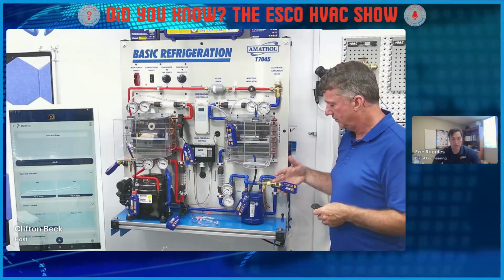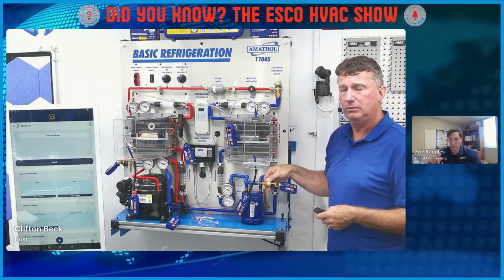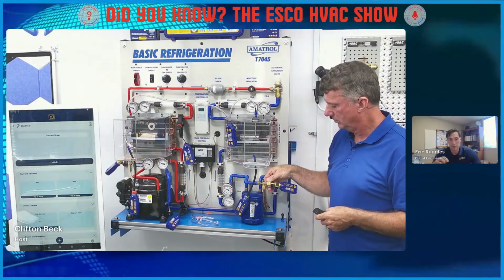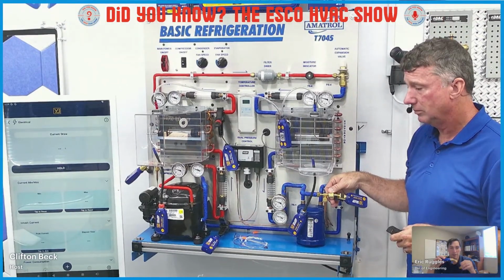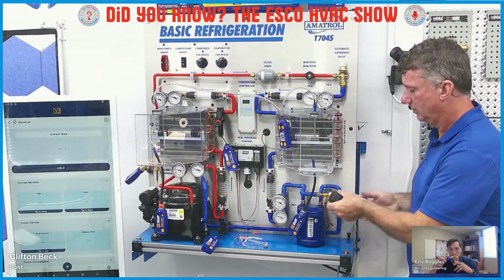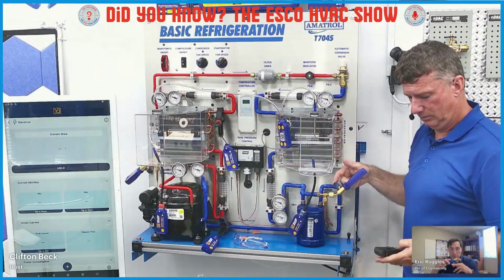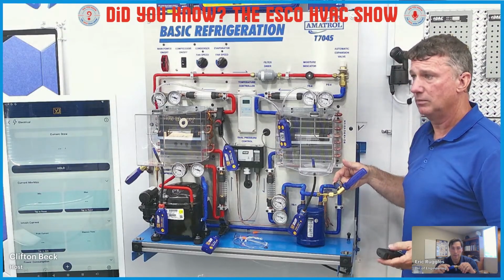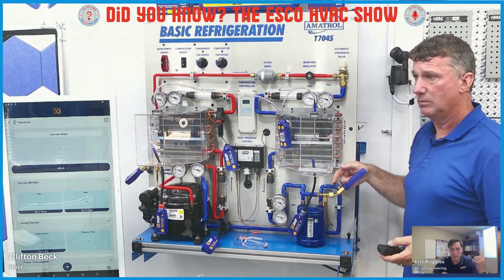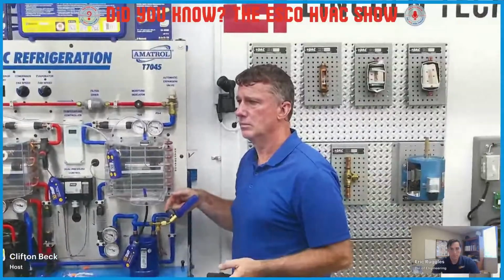So, quarter inch fittings. You can get adapters for 5/16 if you need to, but they just screw on normally with the Schrader core depressor in them. They also have an auxiliary port on the bottom, so there's a T built into it, if you need to add a hose to actually charge or anything through the system. So it's nice to have it built in. But right there, all you have to do is screw it on the Schrader core and then turn it on, which is the little yellow button on the blue screen.